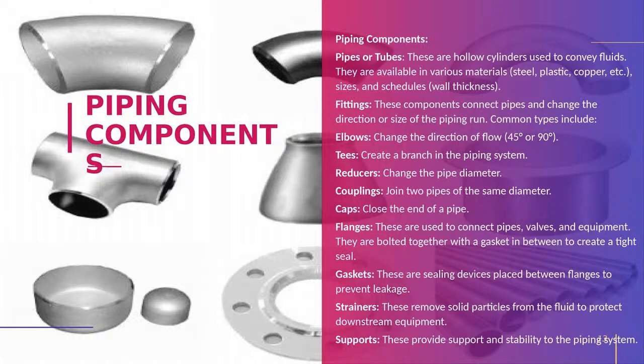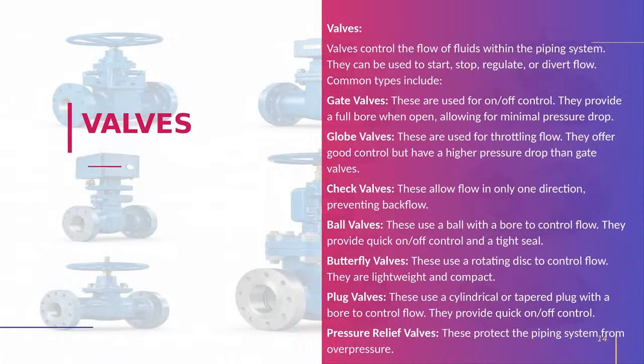Okay, next, Soumya. Like what we discussed, these are the different types of valves that we will see. The gate valve will be used for on-off control only. There are different types, like full bore and half bore. Those valves have trims, and how we select the gate valve with the trim sizes, everything we will see.